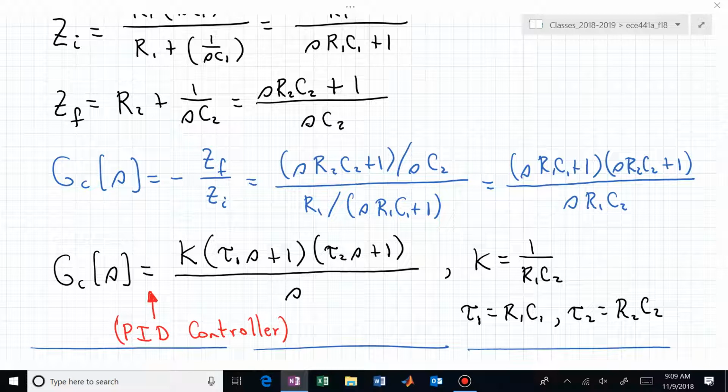Phase lead helps us do what? What's the phase lead help us generically, if you're thinking about it, do for you? Do you remember? What did we say when we wanted to achieve some triangles, some particular dominant closed-loop poles? Oh, our root locus isn't even close to those dominant poles. We need to dramatically change the shape of the root locus. Bing, bing, bing, phase lead, phase lead.